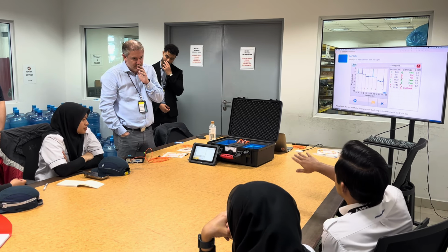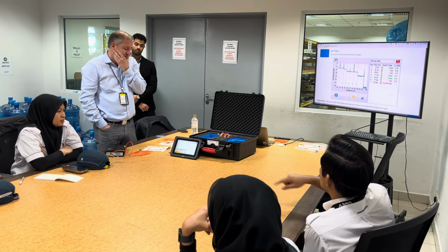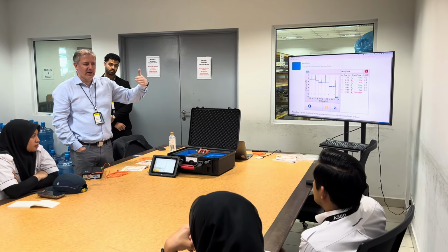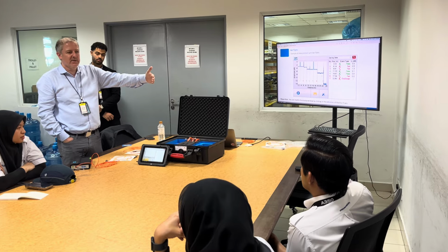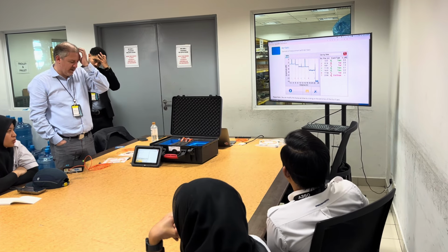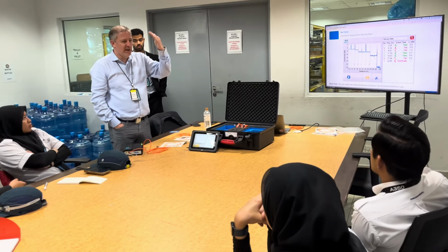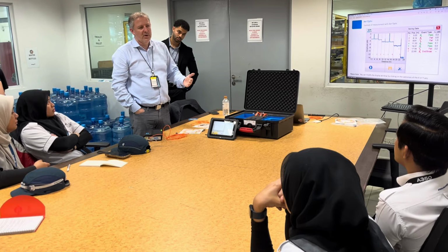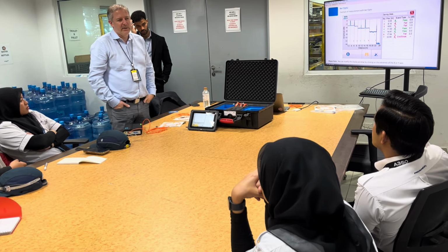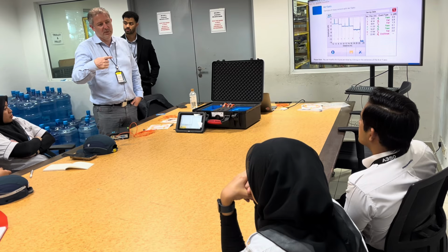Let's say the other end is connected to some component. Do we have to disconnect that before we run the test? It could help you to make sure that you have reached the end, but you don't necessarily have to. But it's gonna help you anyway because then you see the end of the fiber. So if that's the supposed length that you have, and then after, if you have any doubt, you can run the test from the other side too.